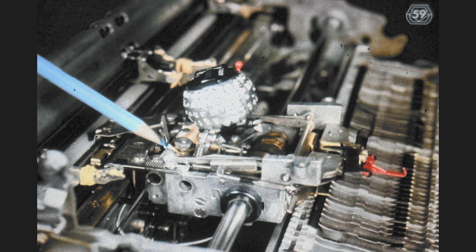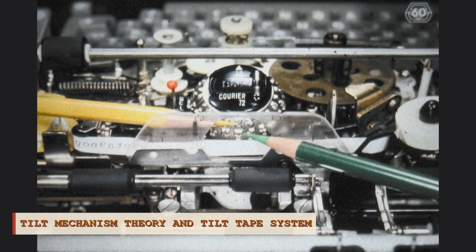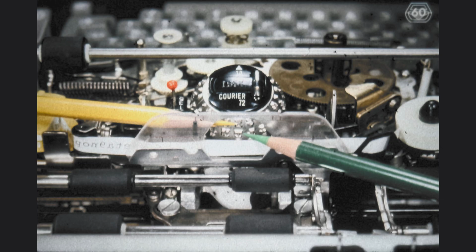The situation is totally different if we observe the resulting changes when the cam follower is in the dwell of the detent cam. We must first change the position of the actuator lever, and then rotate the printing mechanism until the cam follower is in the dwell of the detent cam. We are then able to observe the results.